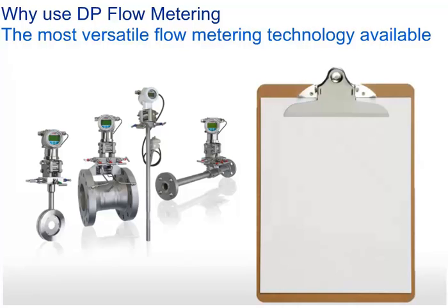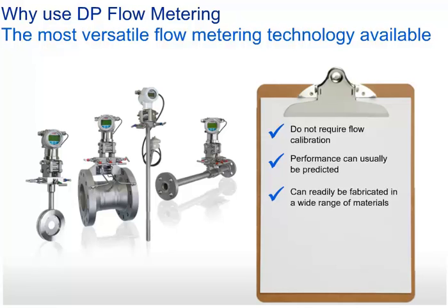DP meters generally do not require flow calibration because their design has evolved from many years of empirical testing and evaluation. This has led to technologies whose performance can usually be predicted by verifying dimensions and ensuring they meet the design standards. They can readily be fabricated in an unrivaled range of materials, including exotic alloys and even plastics.